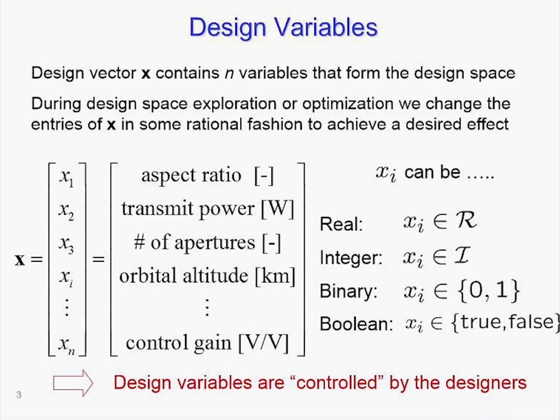So, for example, wingspan was one of our design variables. The lower bound could be 0, but it might even be bigger than 0, and the upper bound might be the limit that we know exists because everything has to fit in a gate constraint, the 80 meter box, say for a big aircraft. Or it may be that we know we want designs that are going to be between 40 and 50, and so we're going to put those bounds on so we don't waste time searching for designs elsewhere. So we may have lower and upper bounds for some or all of our design variables.